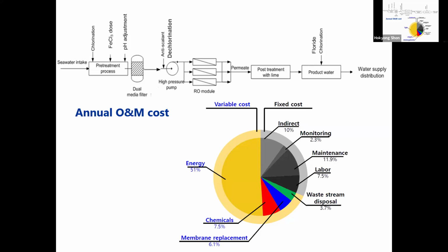If they observe more foulant, they have a higher replacement frequency to make sure of a sustainable flux. But at the end of your module, you don't have much fouling, so 3 to 5 years.